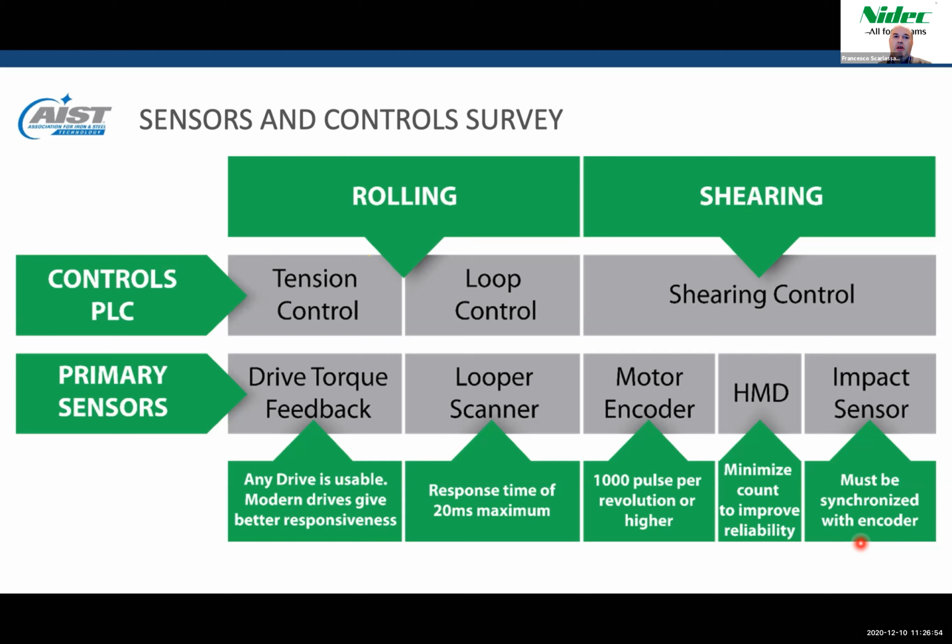And now, shearing control. Shearing control is accomplished with a PLC and does not require any special card for IO computation. The positioning and speed loop can be implemented completely inside the PLC. When the PLC is programmed to provide a torque reference to the drive, then any drive can be used on the mill because we are using the torque reference to the drive.